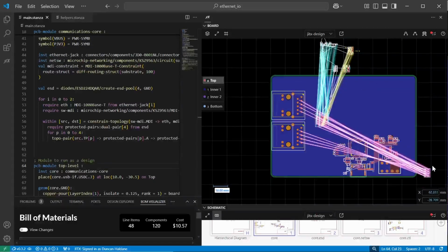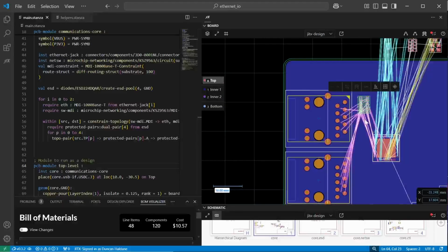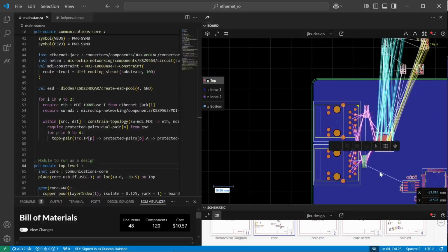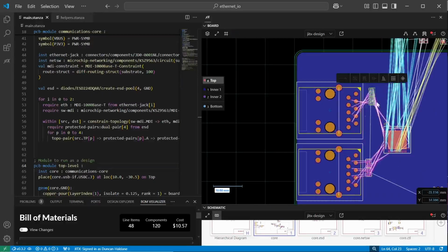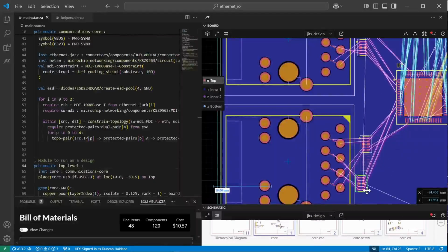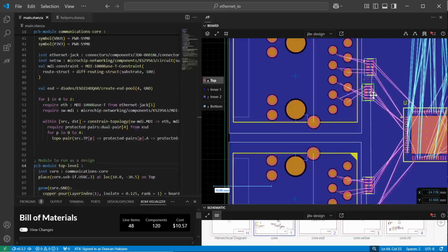Okay, so our old routes were invalid, and now we can have our ESD diodes in place. And notice that all of the connections that go to these diodes are also swappable. So we don't actually have to figure out which diode goes with which signal and then edit a schematic. We can rather position them in place and have our code that constrains the topology and the loss and skew just flow right through these diodes.